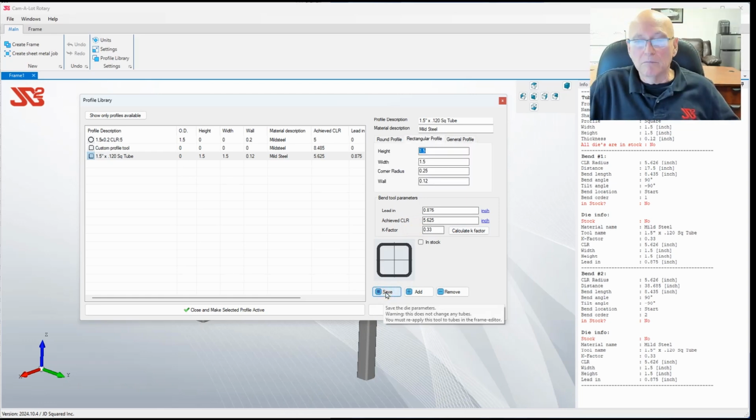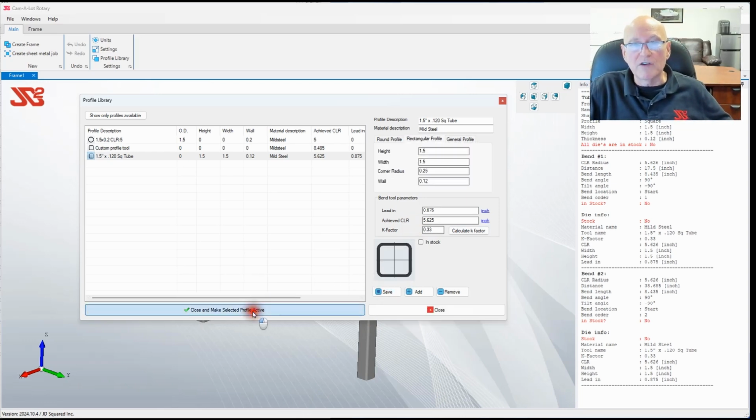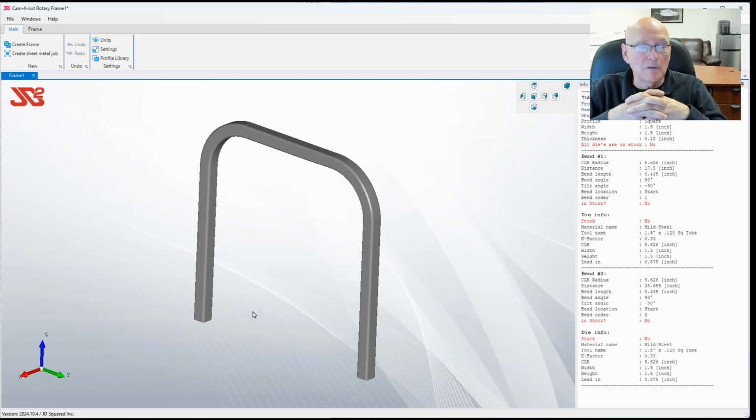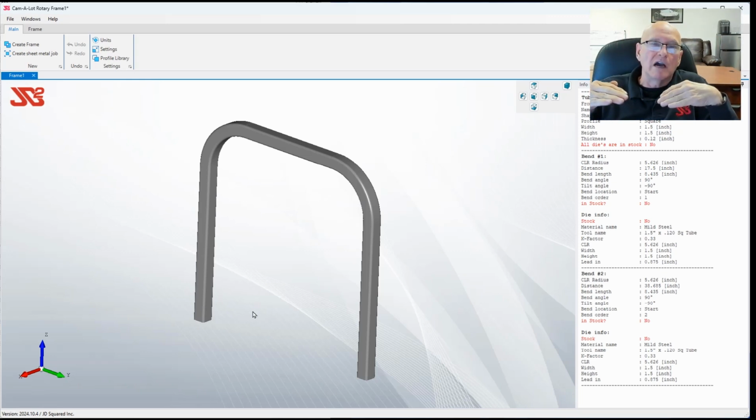Anyway, that, believe it or not, is about everything that I could think of telling you about K-factors. It's a little black magic doing bending because you're dealing with different hardnesses of material. Bottom line is, don't expect perfection. Pretend you're working in a grenade factory, because whenever you bend anything, you're not going to bend perfect 90s. You're not going to have perfectly heat-treated metal. You're not even going to have perfect thicknesses. If you get a piece of square tubing that has a welded seam on it and it bulges up on one side, even that could affect it a slight amount.